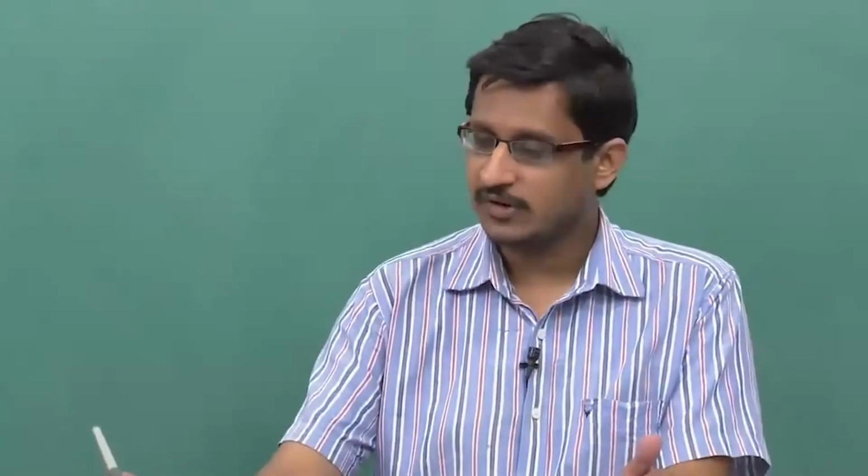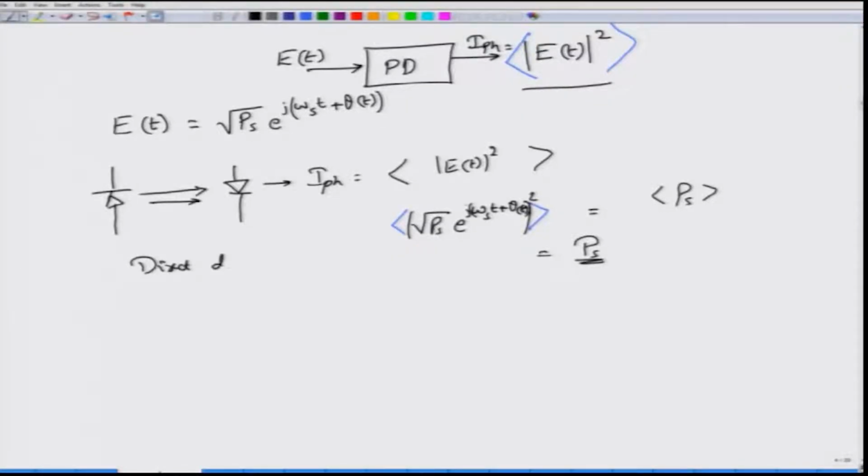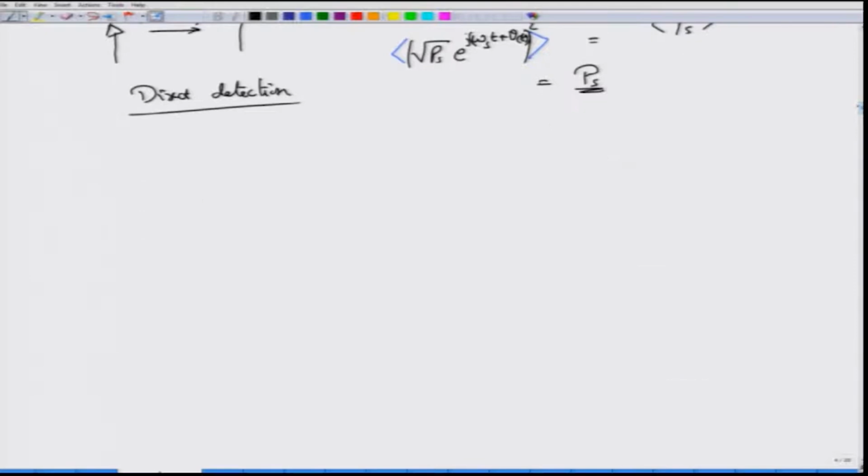Okay. Whatever we have done by putting up a laser and a photodetector is known as direct detection. Even today for 10 Gbps to 40 Gbps data rate systems, laser intensity modulation and direct detection is the simplest, hardware efficient and most widely understood and implementable detection receiver topology. All that you have to do in direct detection is simply put a photodetector. The optical signal comes and falls on the photodetector and you simply generate the photocurrent.